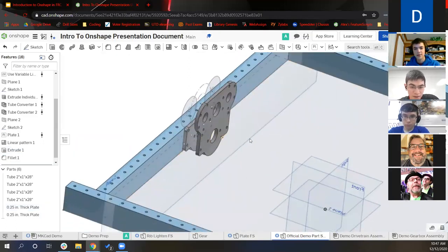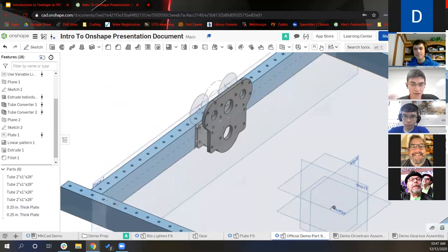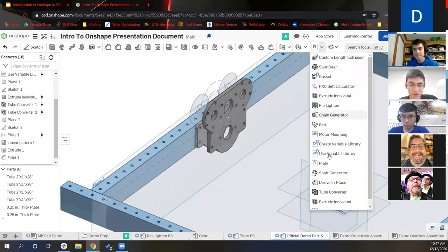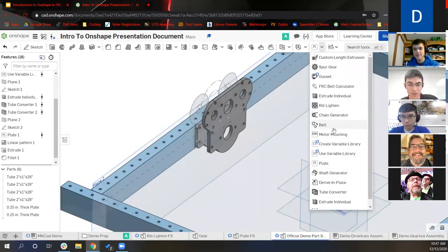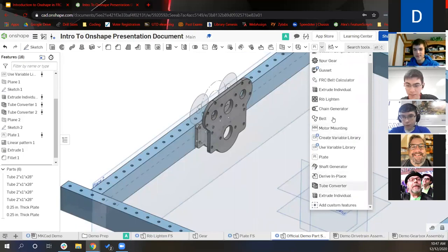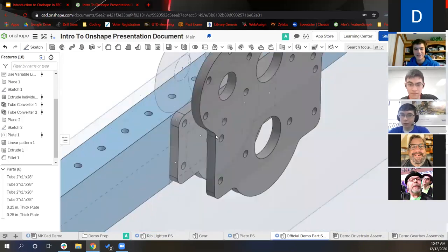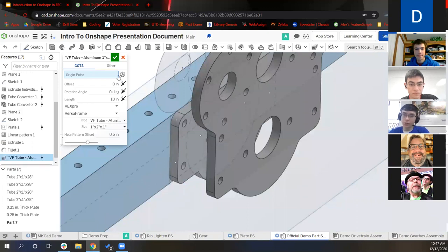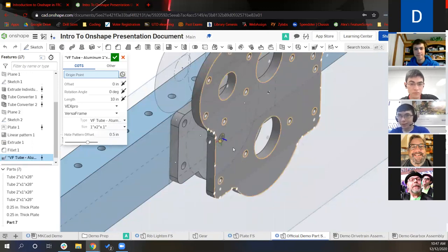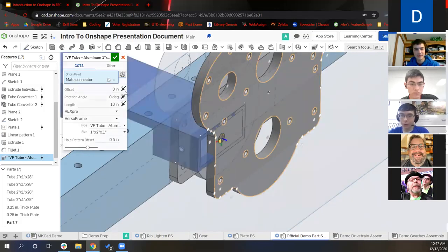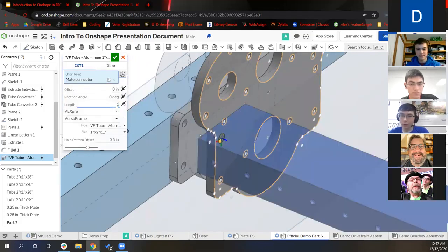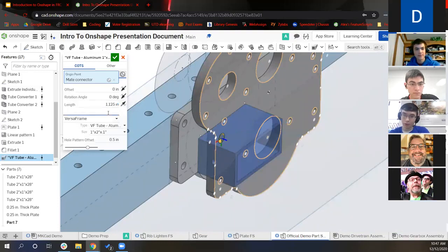Okay, like so. The really nice thing about how we designed this is everything is parametrically linked. So if you update that first gearbox plate, the second gearbox plate will update. If you move your holes or anything like that, both gearbox plates will always mesh really nicely. So far we're up to only two sketches, and it's approaching a full drivetrain. You probably only would need one more to put the other bearing holes in the tube, and you'd have pretty much a complete drivetrain.